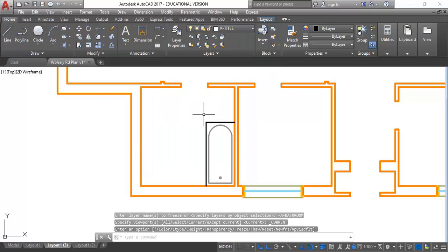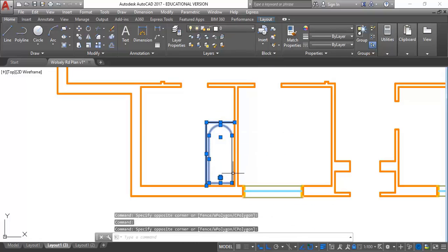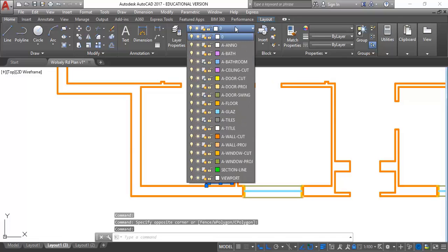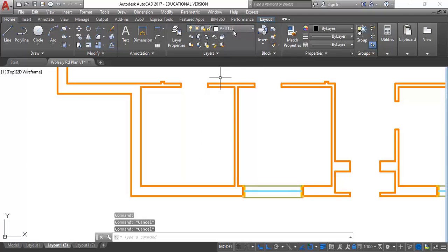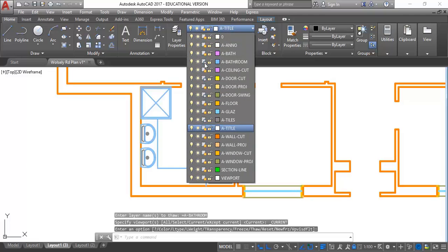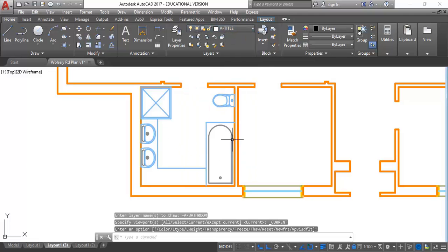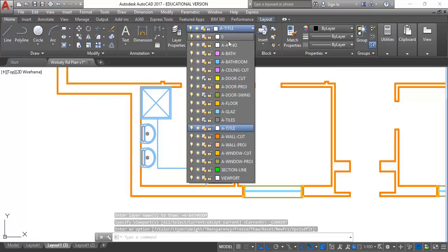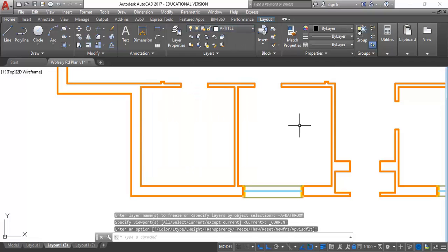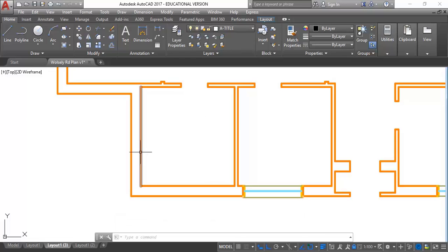Oh, no, why? Because sometimes you want to have a spotlight just on top of it. That's right. So in that situation, what you would do is just unfreeze that layer so that you can position your lights, but then you would still turn it off for the finished drawing because you don't want to see bars and other things covering up your ceiling objects. The purpose of this drawing is to show what's on the ceiling, really.